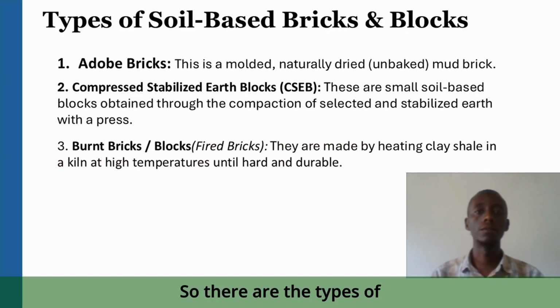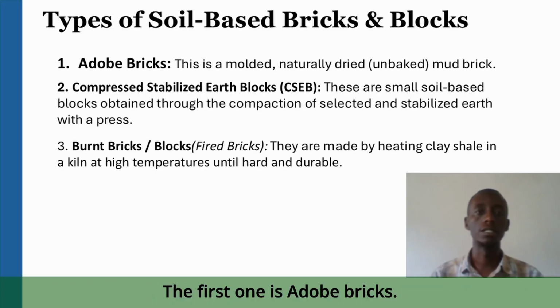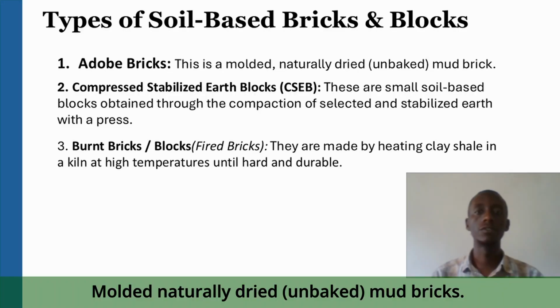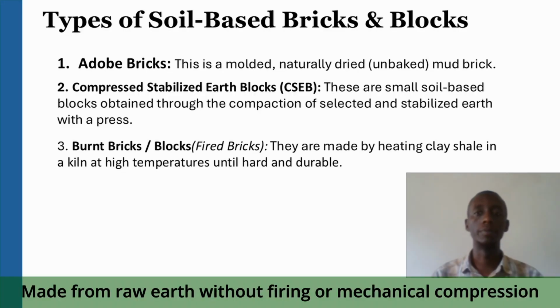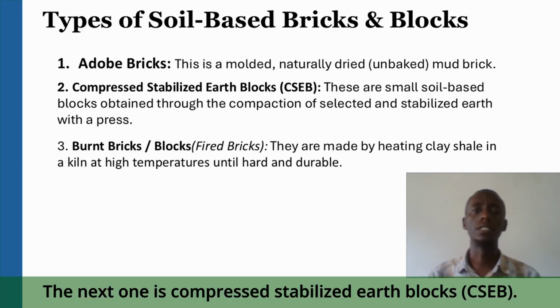So, these are the types of soil-based bricks and blocks. The first one is adobe bricks: molded, naturally dried and baked mud bricks made from raw earth without mechanical compression, traditional and widely used in local construction. The next one is compressed stabilized earth blocks, which is CSEB.